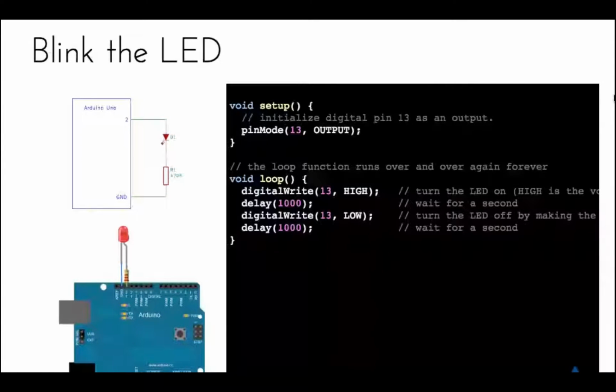How does a basic Arduino program look like? It's a very simple program. You say setup, where you set the mode of the pin. There are like 13 pins here and 5 or 6 pins here. Out of these 18 pins, you set the mode of the pin, as an output or an input. Then you can write its value as high or low, and it would blink an LED. It's a very simple program. Probably I can demonstrate that to you. It won't take more than 2 minutes. You can actually start counting.